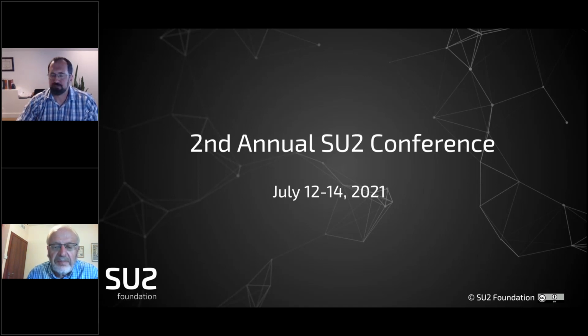Okay, and Pei Defana asked, I have two questions. The filtering in the hybrid RANS-LES is implicit or explicit? And second, for wall model LES, how do you find the h_wm? So the filtering, I believe, is implicit. It's based on just the mesh spacing, but I will double check with Eduardo on that.